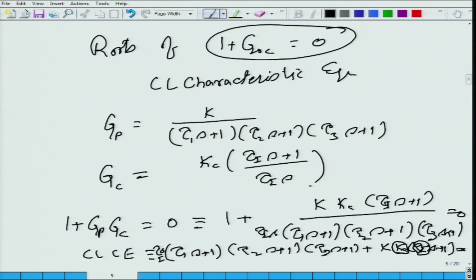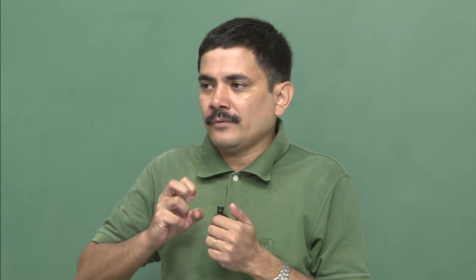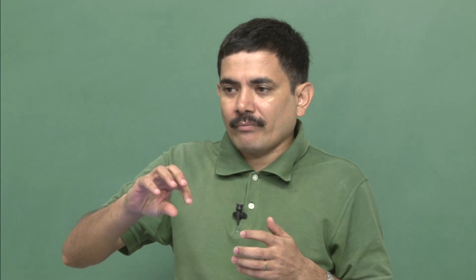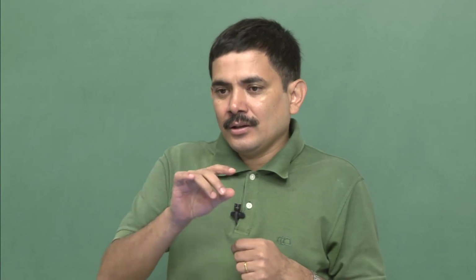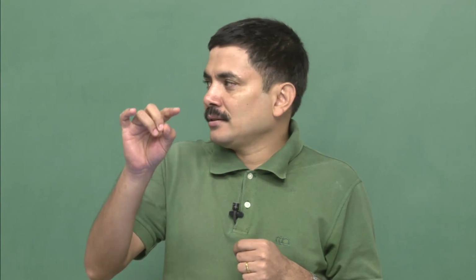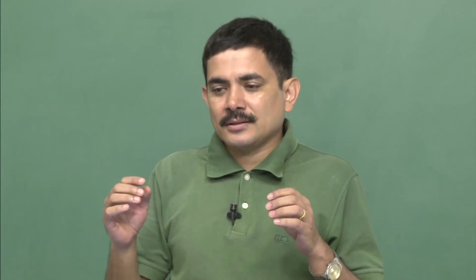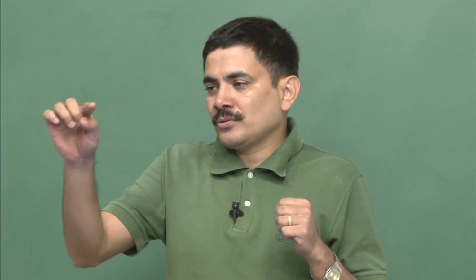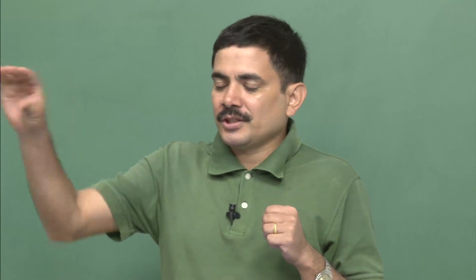So, what you will find is that if you have a feedback control system for this third order system, and let us say you have fixed tau_I and you are just changing k_c, when k_c is small, all the roots of the closed loop characteristic equation are real and in the left half plane, that means real and negative. Then as you crank up the k_c, you will start seeing that the oscillations are coming, and these oscillations decay in time.